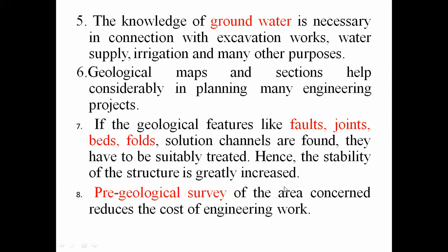Okay. If you are going to take a foundation and that foundation goes below your ground water level, then it will be problematic because your foundation always comes in contact with water. And slowly the water is percolated from the concrete also, inside that structure.